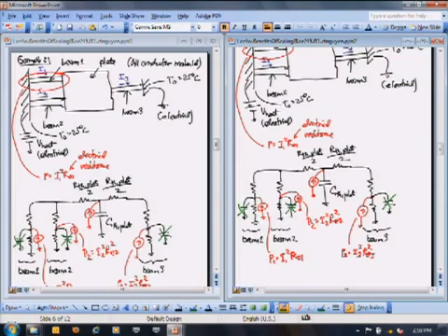And because the plate has this length to width ratio that isn't so big, it's also not going to be very resistive. And so the heat that's being dissipated in the plate is going to be very little compared to that dissipated in the beams. So I'm also going to neglect that power source. Now, unfortunately, all the rest of this you will have to analyze.